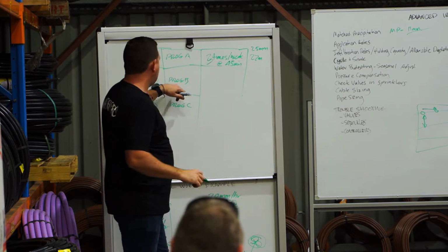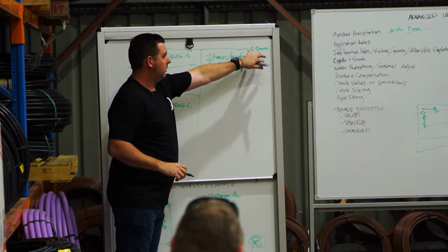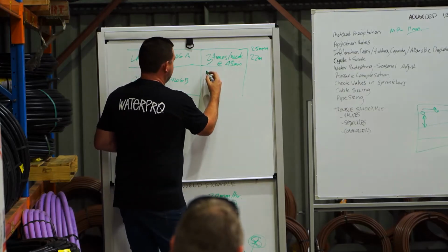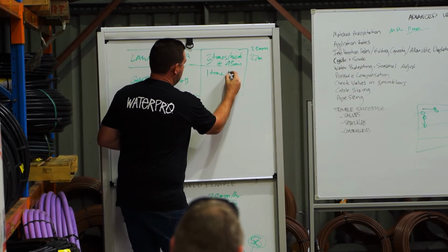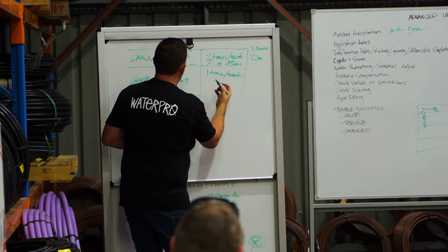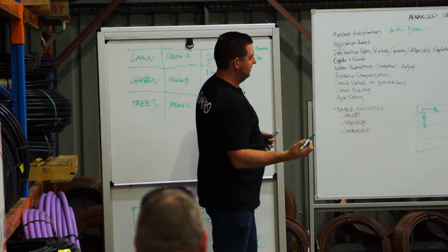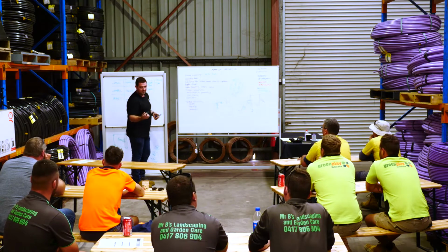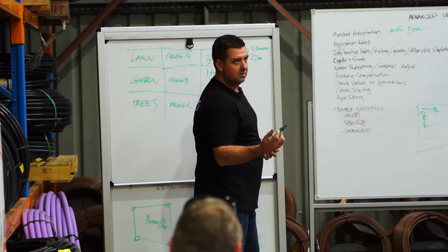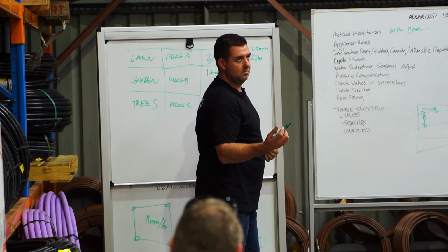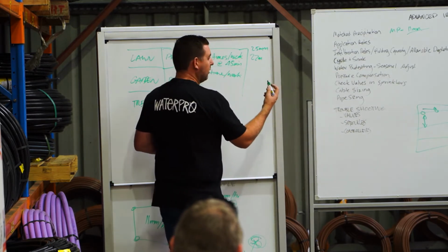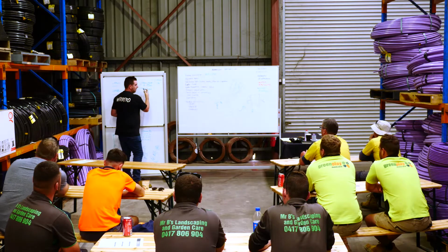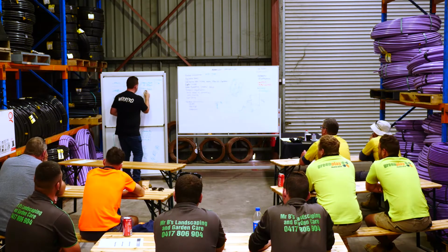And then the garden, say we wanted to get the same amount of water, we might want to water the garden just once a week. So we're going to set that to water 1 time per week. So who can tell me how long for at 20 mil? If we want 25 mil, say, what's 5 over 1.1 hours or something? 1.15 hours? Hour and 15, we'll say, so 75 minutes for this one.